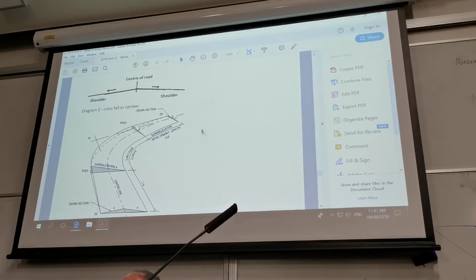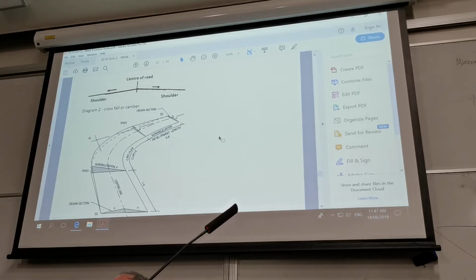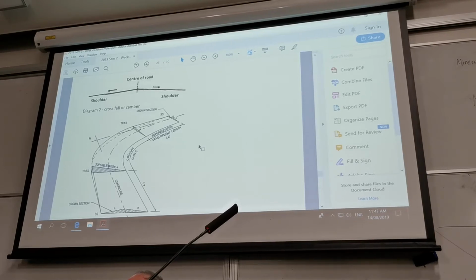Those tracks, just like the bike tracks in the Olympics, always have a very good circular curve on them, and a very good camber on the road. You'll notice that the camber starts at about 3 degrees both ways. Then it works its way to a full camber from here to here, and then goes back to -3 degrees on both sides. That basically goes from the start of a circular curve to the end of a circular curve. On more complex roads like motorways, we have a spiral curve leading into the circular curve. Engineers will go on to do that in highway and motorway design as well. But that's just a basic drawing introducing you to super elevation and camber.